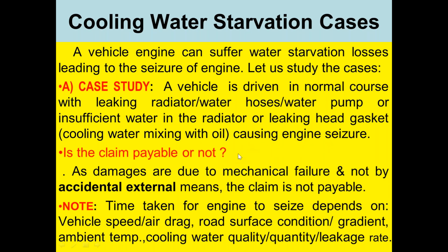Is the claim payable or not? As the damages are due to mechanical failure and not by accidental external means, the claim is not payable. Please note that the time taken for the engine to seize again depends on vehicle speed, air drag, road surface condition, gradient, ambient temperature, cooling water quality, quantity, and the leakage rate.